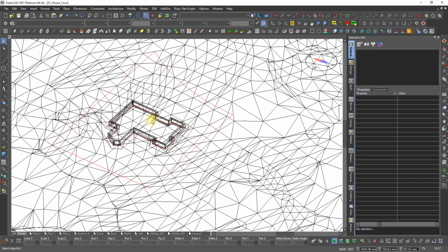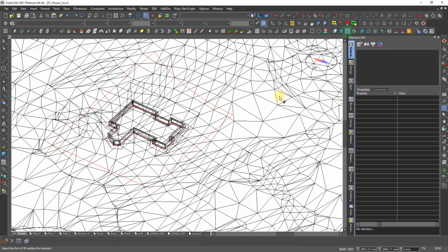But I don't want to make it disappear, I want to keep it. It's important that the box is solid, not the surface. If it's a surface, you don't cut out the same way, I believe. So then I take this, I want to have intersect. I want to keep what's left in there. And I say keep the origin, don't delete it.